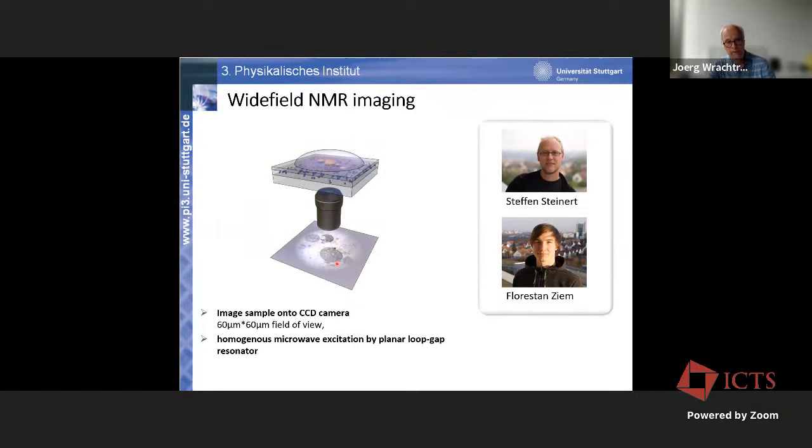So in a nutshell, the central part of the overall imaging device looks like this. You have your microscope objective, you have a detector, which is a CCD, you have your layer of diamond dopants. The fluorescence intensity of these dopants, these NV centers, depends on the local magnetic field of the specimen on top of the chip, and they convert this local magnetic field into a local fluorescence intensity, which you then measure on your chip.